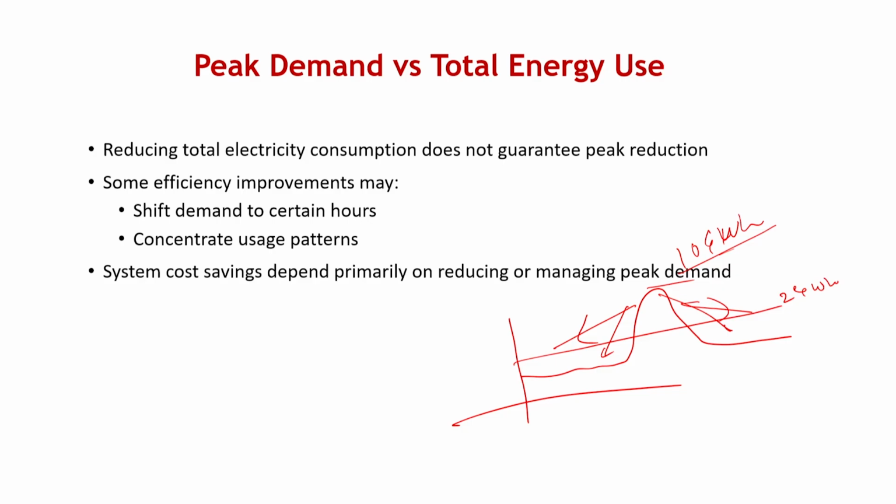That, in a way, is distributing the system in the right way, so that I can remove the concentrated use of power. Because if I can reduce this peak from 10 to, say, 4 gigawatt hour, then I will need to design my system only for 4 gigawatt hour instead of 10 gigawatt hours. That will reduce the system cost, and it will also help maintain the system in a much more efficient way, because my generation and my consumption can have better overlaps.